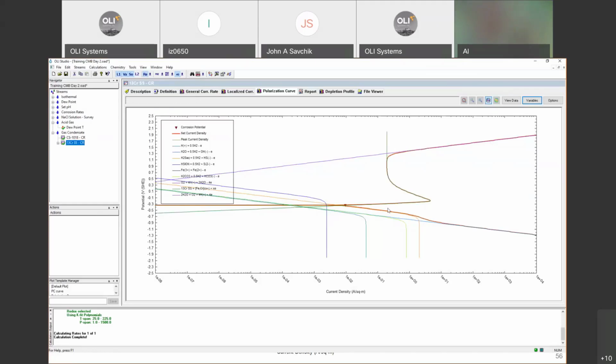the response of the current density for 13 chrome, and probably that is because 13 chrome has chrome in the composition, that the alloying element is chrome, and that will contribute to reduce that current density. And only one or only two different reduction reactions are adding to this corrosion potential. So that's the reason why we are seeing a lower corrosion rate here for this specific alloy.